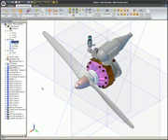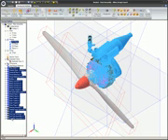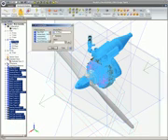In this case, we're going to include all the parts and subassemblies in the assembly. The main shaft is selected in the Design Explorer, the Shift key on the keyboard is held down, and when the propeller assembly is selected, the entire list is selected. Now Section View is clicked on the Viewing and Analysis ribbon.